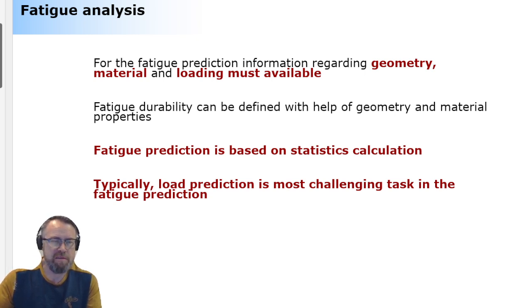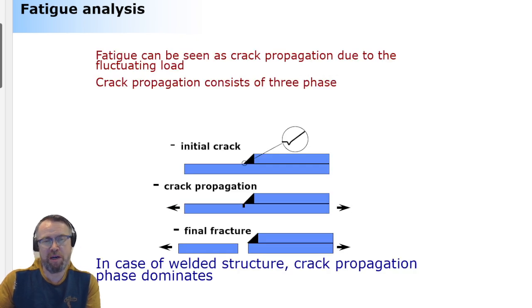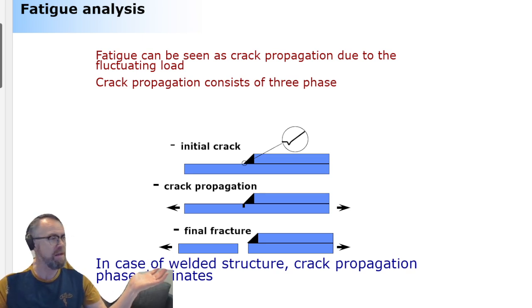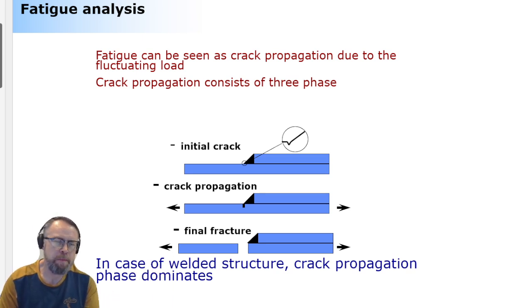Okay, fatigue life or damage, how it is evolving, consists of three things: crack initiation, crack propagation when the crack is growing in a structure, and then what happens in a fraction of a second, the final fracture when things are separated. So those are the three phases.